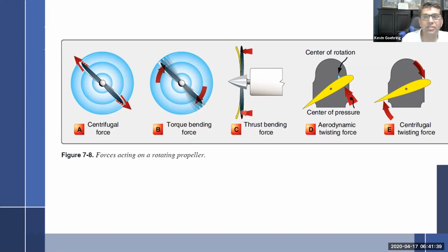It's actually false. I've talked to prop shops who have said they've seen propellers almost get ruined, especially on a hot day when the metal's really hot and pilots put their hand out here somewhere and start pulling on the prop. It bends it forward and throws out the tracking. Then it starts to get inefficient and all kinds of problems.